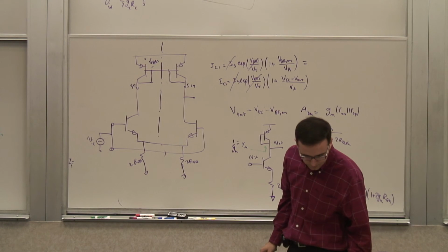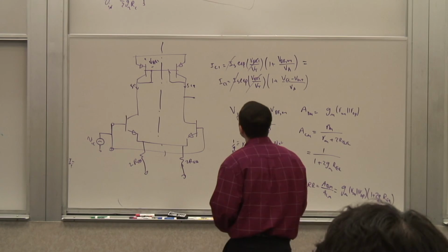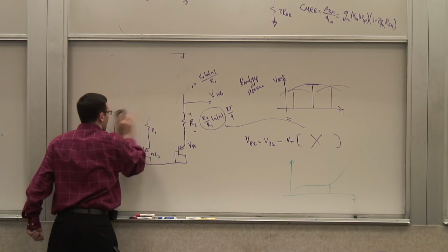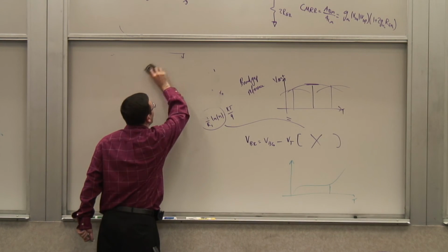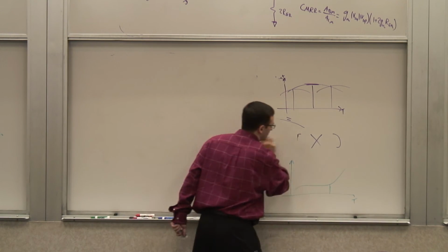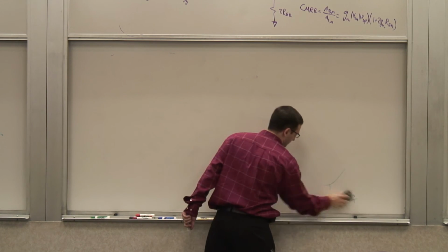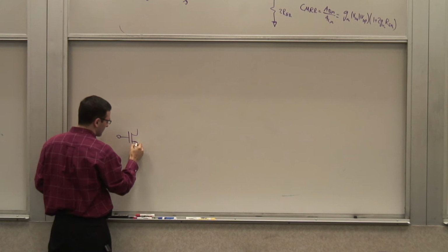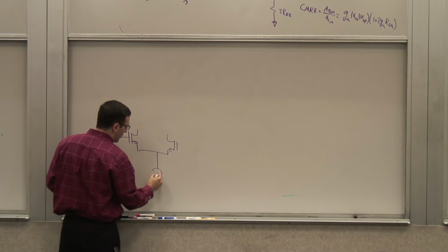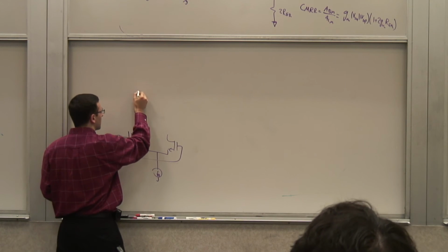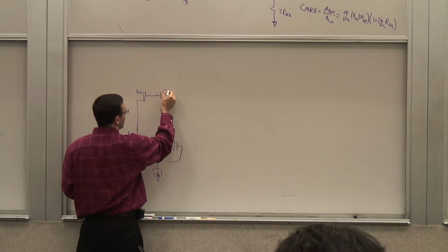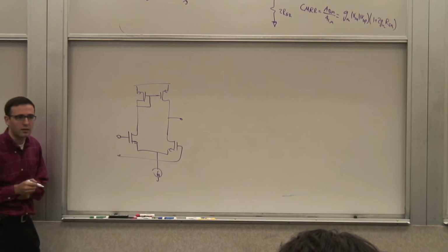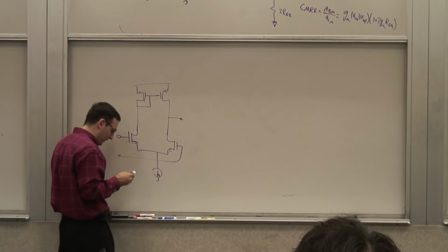Now, you can do exactly the same thing in MOSFETs, with a MOS differential pair. And we can quickly do that. The MOSFET pair would look like this. And then, of course, if you want to convert the differential to single-ended, then you can use a MOS current mirror. And you can see, a lot of things are very similar. They're kind of parallels of each other. So you can do exactly the same thing here. And the idea here is, again, what is the gain? If I ask you what is the gain of this stage?